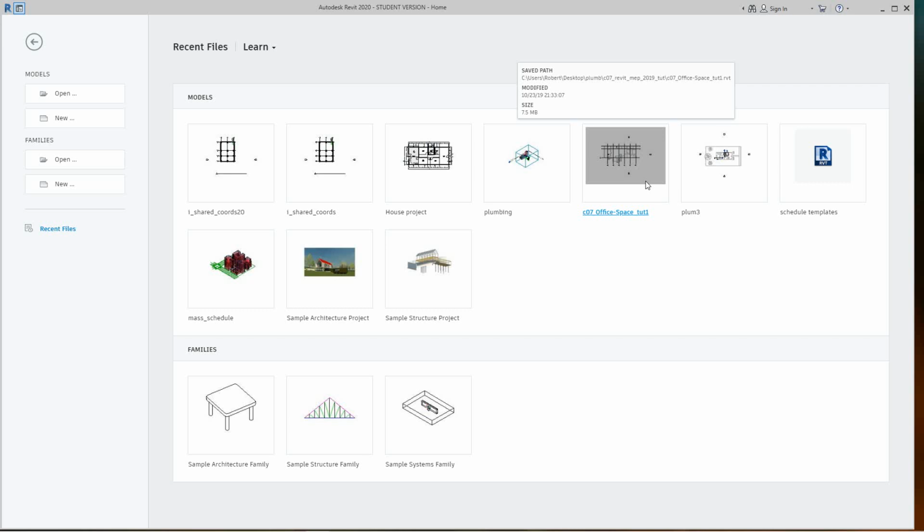A survey point represents a known point in the physical world, such as a geodesic survey marker or benchmark, or whatever they use. The survey point is used to correctly orient the building geometry in another coordinate system, such as the coordinate system used in civil engineering applications.